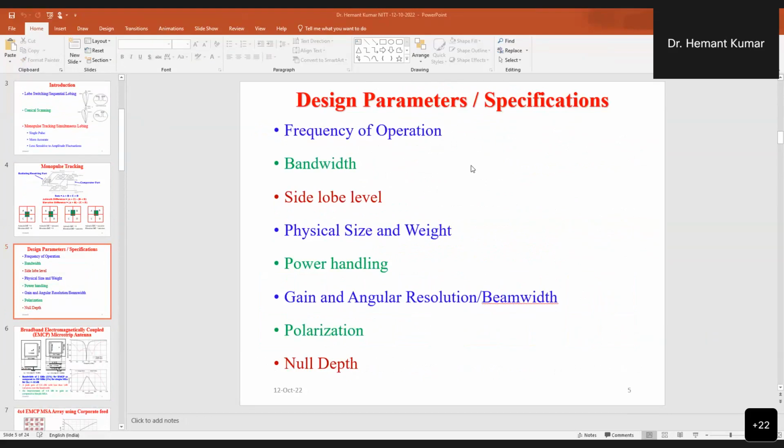If you are working at millimeter wave frequency and you want to mount your antenna on a platform where heavy weight is not possible, and you also want to use the horn antenna, then in that case you can go for a SIW horn antenna. In case you don't have any physical size constraints, then you can use a 3D horn antenna also. So it all depends on the application, the platforms and the functions for which you are designing your antenna. For biomedical application, if you can tell me how much bandwidth and what the constraints are, based on that you can choose which antenna.